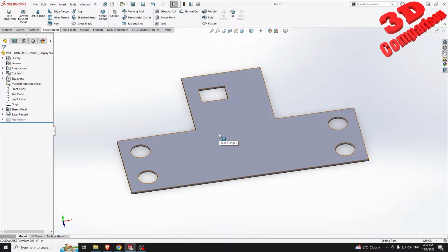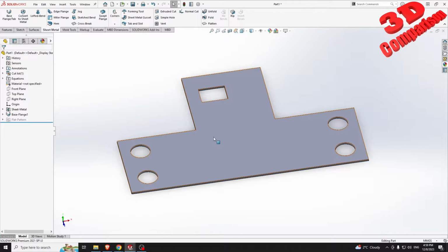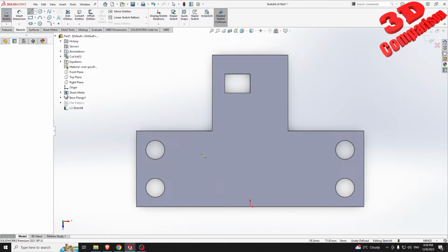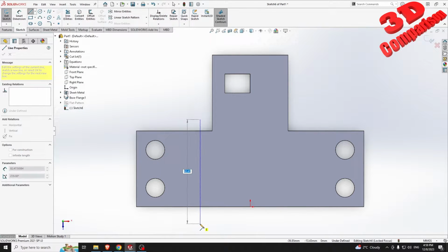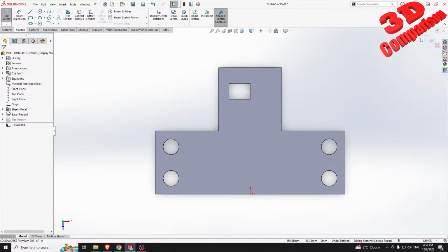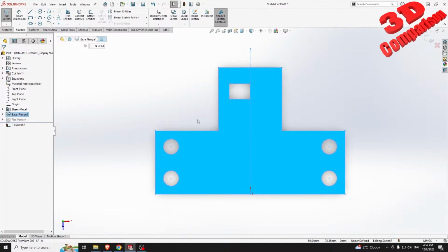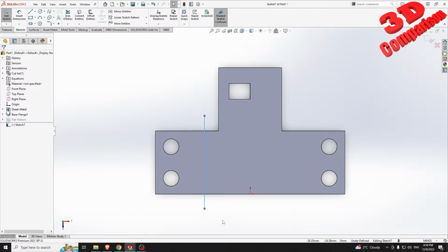And now, if you wanna add those bends, we're gonna have the possibility to use this sketch bend. I will select the top face of the part, and over here I will create a line. It's not important that this line should be coincident with the existing sketch. Let me take a look at that sketch and why exactly is the line disappearing. So I have the line created. Afterwards I will press escape, because that line shouldn't disappear, but my mouse is a little bit buggy.